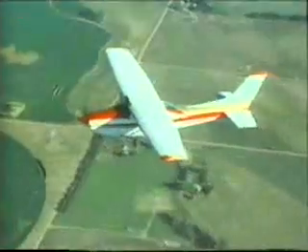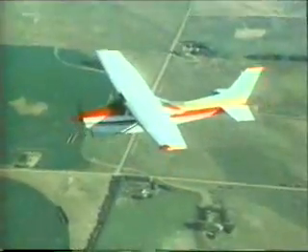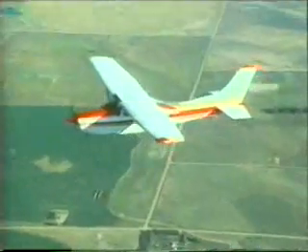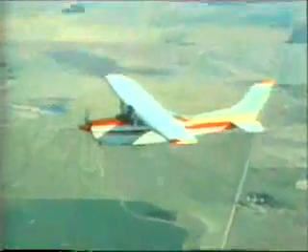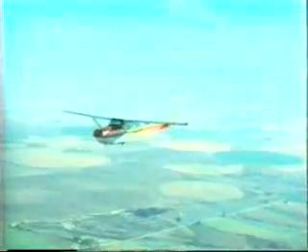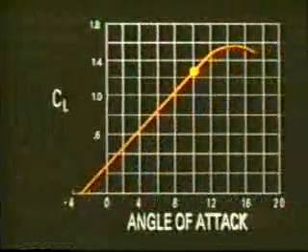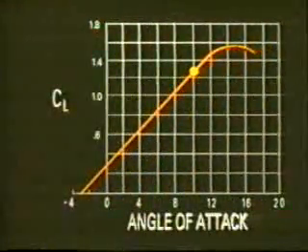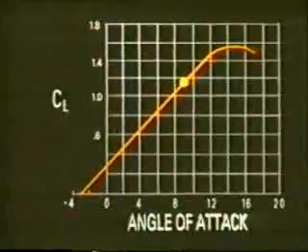However, if you double your velocity without changing the angle of attack, the airplane tends to climb if trimmed for a slower speed. Therefore, in order to maintain altitude and balance the forces in a state of equilibrium, you must decrease the coefficient of lift as you increase velocity. As the graph shows, you normally lower the coefficient of lift by lowering the angle of attack.